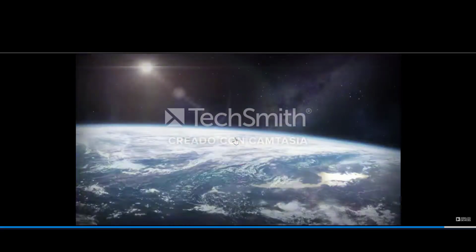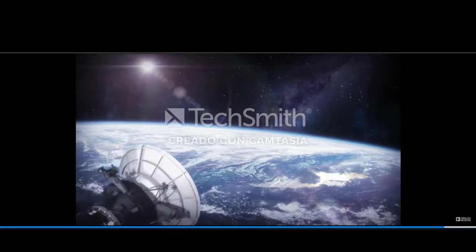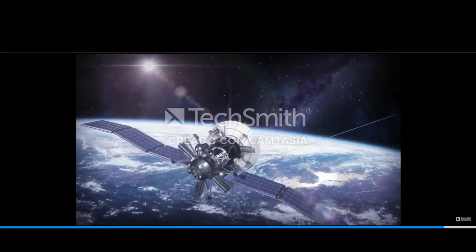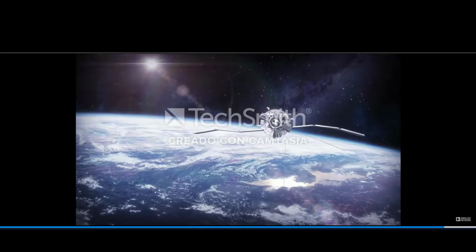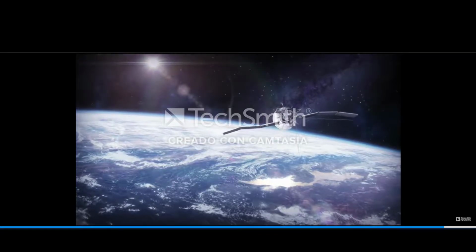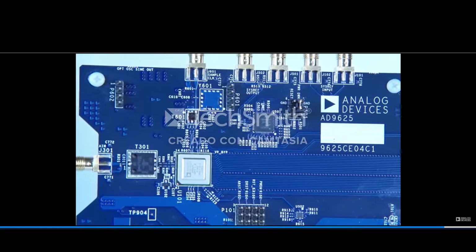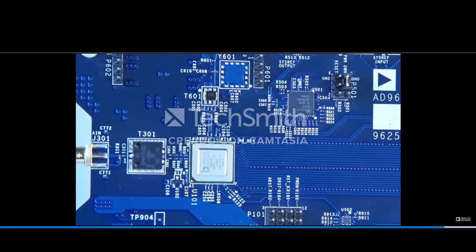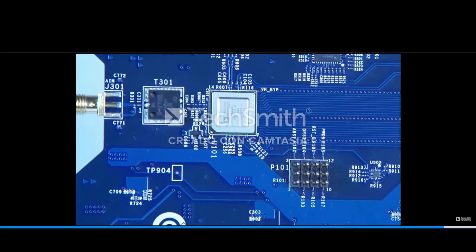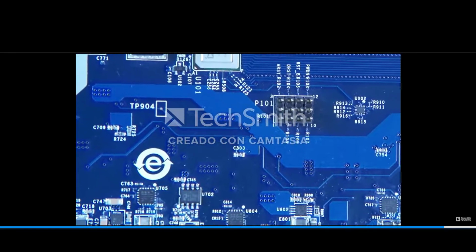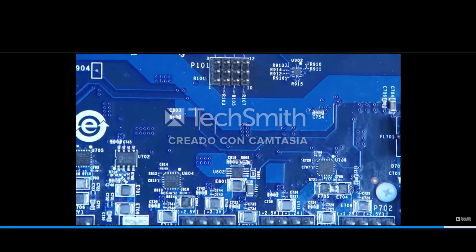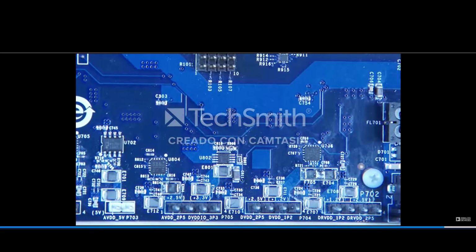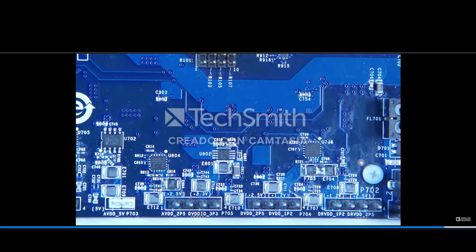High-speed analog-to-digital converters have evolved into the gigasamples per second realm with a corresponding increase in usable bandwidth. These performance improvements come with a number of challenges, one of which is more complex power supply requirements. For example, the AD9625, a 2.6, 2.5, and 2.0 GSPS sampling ADC, requires 7 independent power rails divided into various voltage levels.